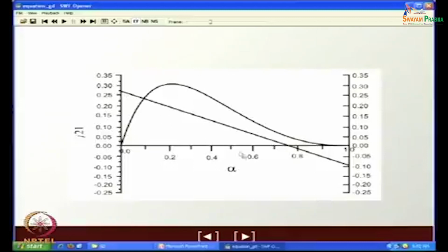What happens? The curve will be intersecting at lower and lower points. From a fixed J2, naturally we find that the point of intersection will slightly shift towards lower and lower alpha. Quite expected. Higher liquid velocities, naturally in that case we will have a lower alpha.